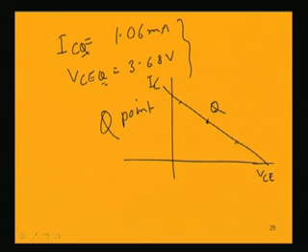In this whole discussion we have discussed different biasing schemes. We have seen that the potential divider biasing scheme has more flexibility, and it is insensitive to beta as long as we maintain a particular design condition with respect to the resistances being connected. Until that limiting condition is satisfied, we can make the operating point insensitive to change in beta.